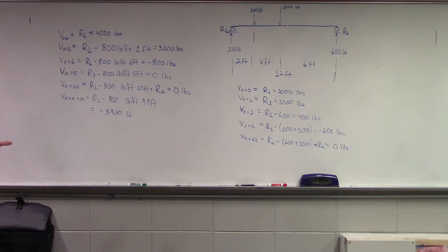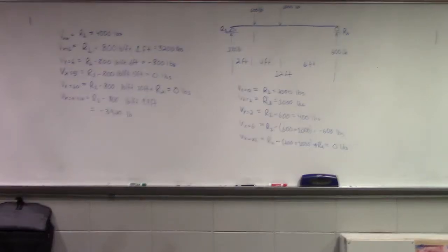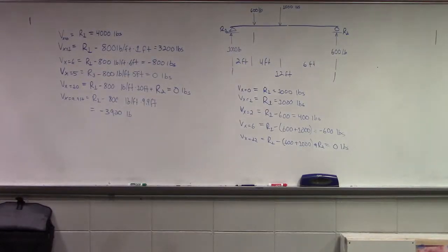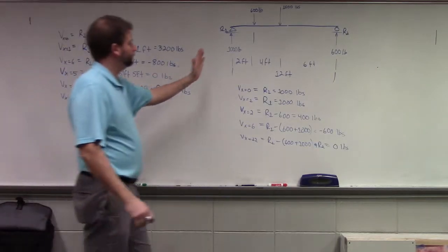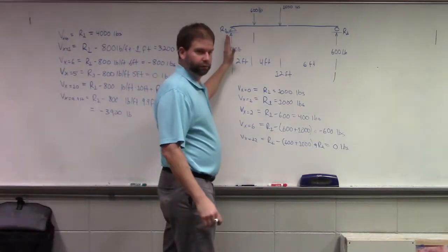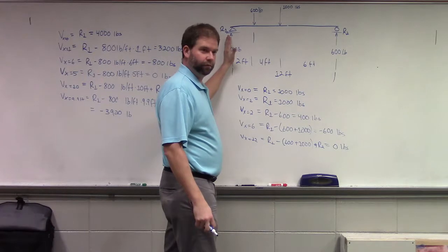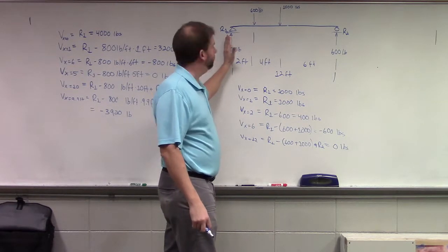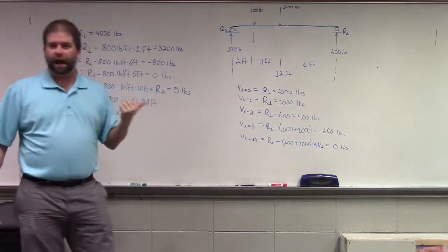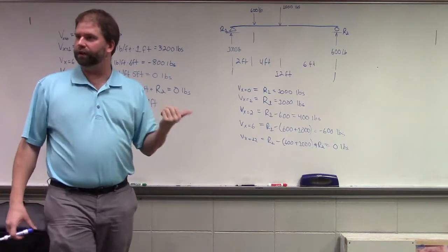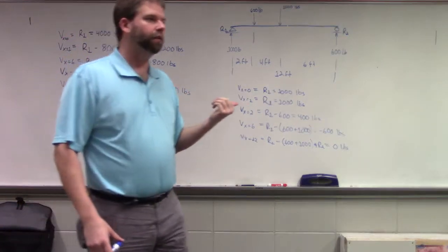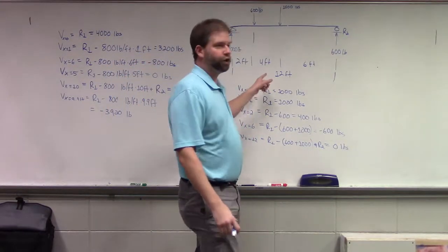So in this case, where does our maximum shear occur? I'm gonna say R1. R1, right? Yeah, I was thinking about 0. Okay. Because we don't have a uniformly distributed load in this case, we won't have anywhere where we'll have 0 shear, right?